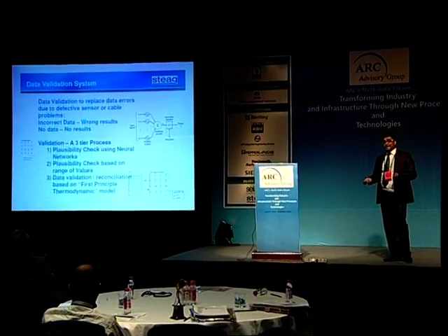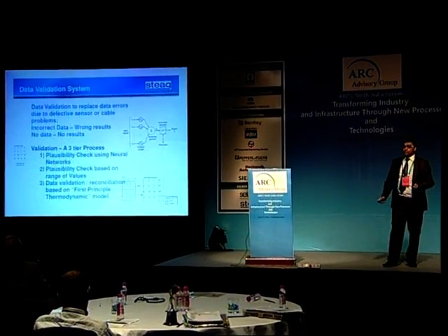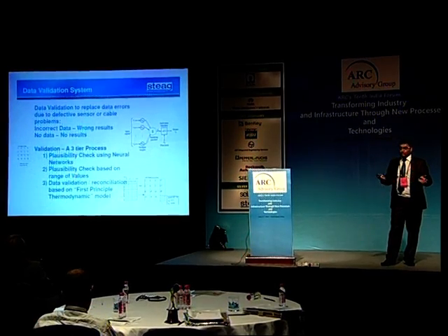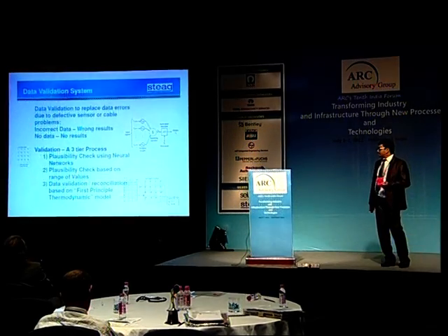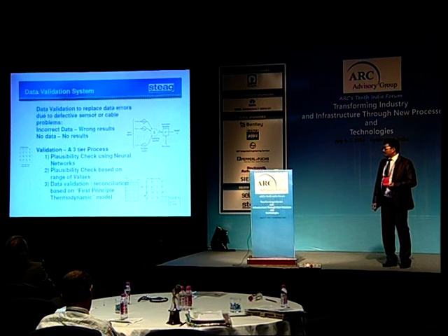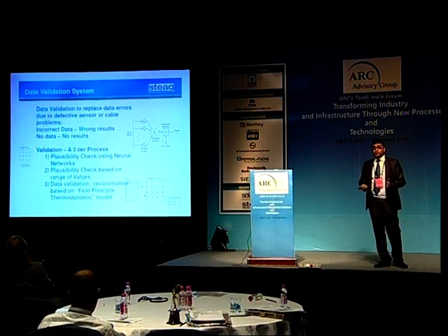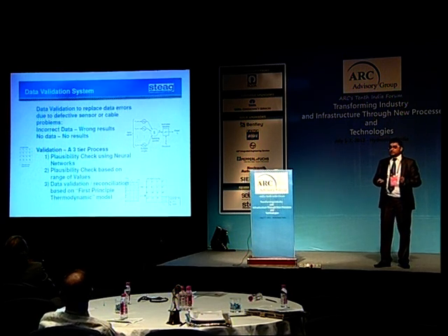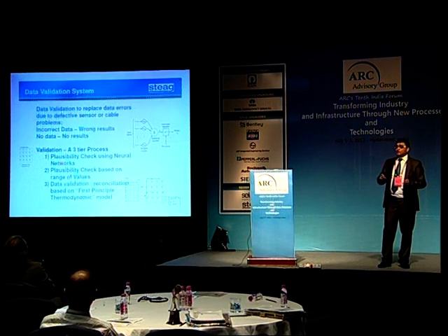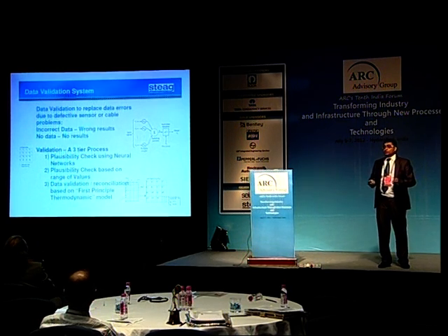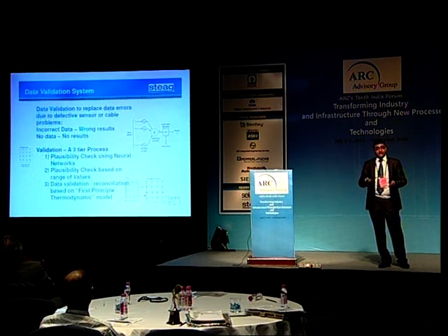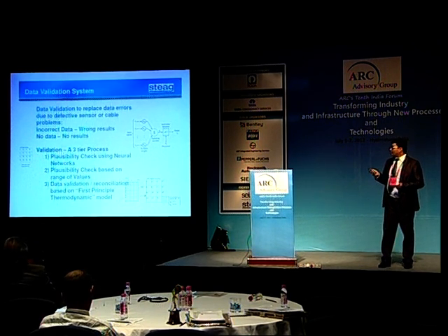So we provide a range check validation also, where based on the current load conditions and everything, the input data can be validated. But the third and most important data validation which we provide is the first principle based thermodynamic modeling tool. As I said, we have Epsilon, which gives you the first principle mass and energy balances. It also has the inbuilt VDI 2048 standard. That means that's a validation standard internationally recognized. This Epsilon provides that kind of data validation.